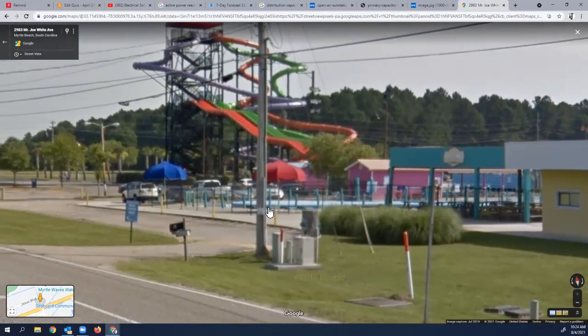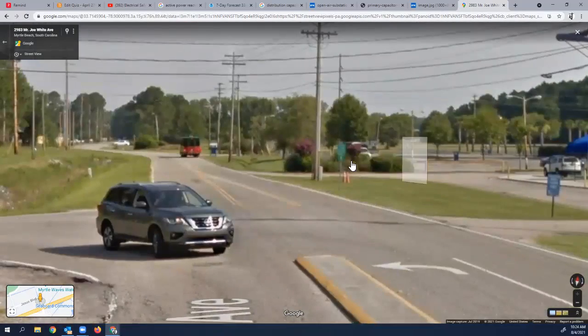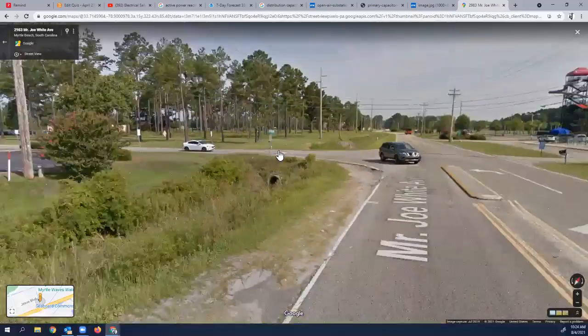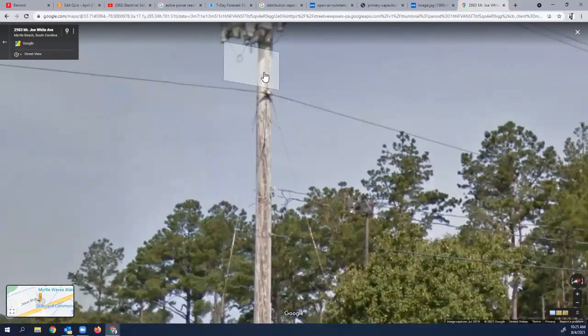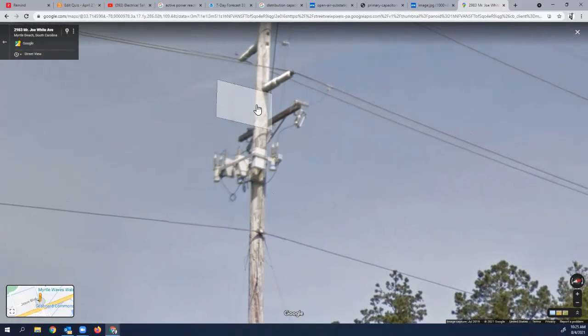The controls, that little gray box, are way over here. We'll talk about this in just a moment. So SCADA is talking to the radio, and controls are in this panel right here, I'd say 100 feet away from the capacitor bank. We'll get into that reason in just a moment. Is that in case a car hits it? No, no, it's for your safety.